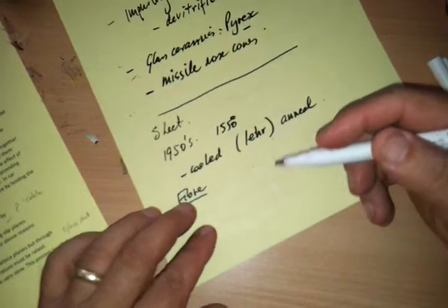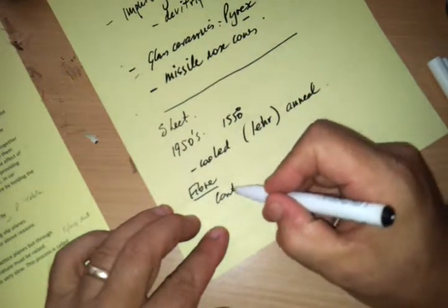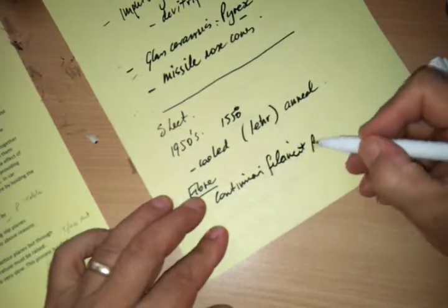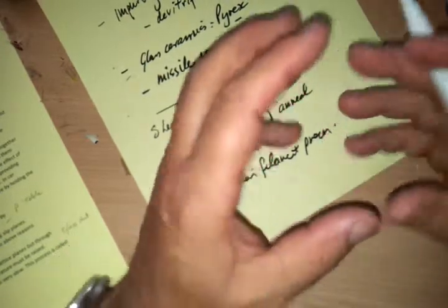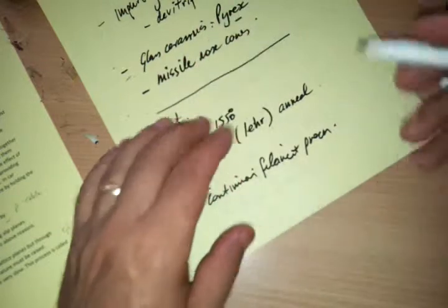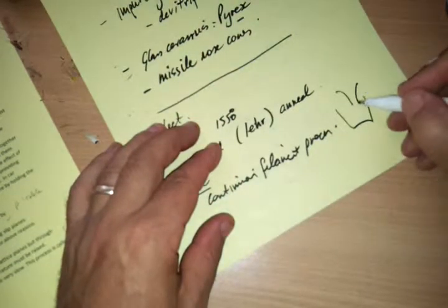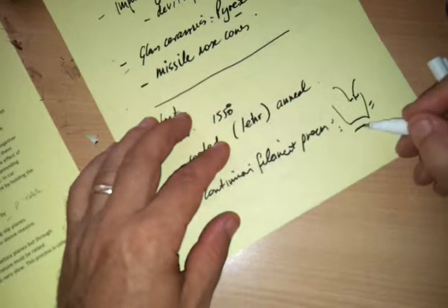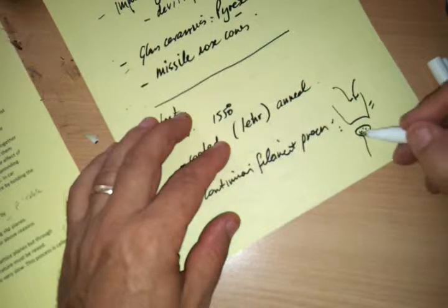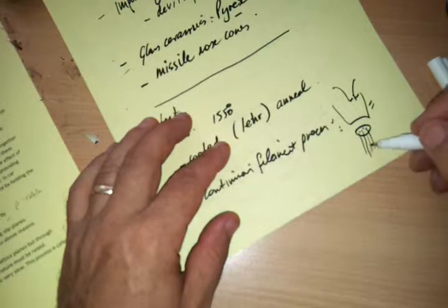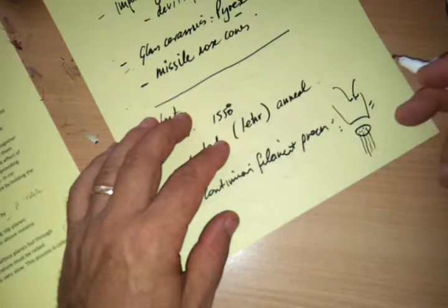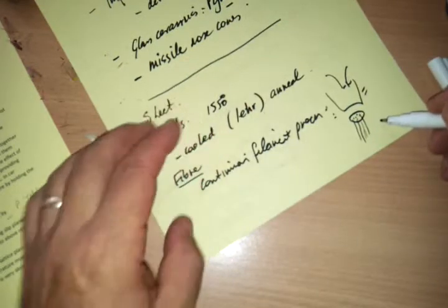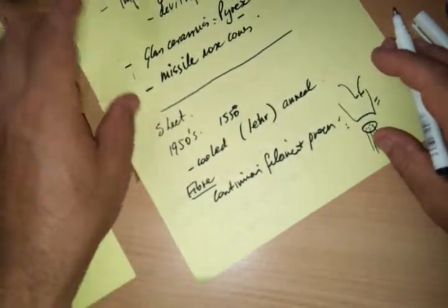One of the most common ones is called the continuous filament process. That's where glass marbles, which are the raw glass material, are fed into a heated hopper, and the material is then pushed through a base which has lots of small holes in it, and the filaments are drawn forth from that base, and then they're wound together or stored on a drum, or sometimes they're spun into a shape or webbing or a matting or a tape. So that's the continuous filament process.